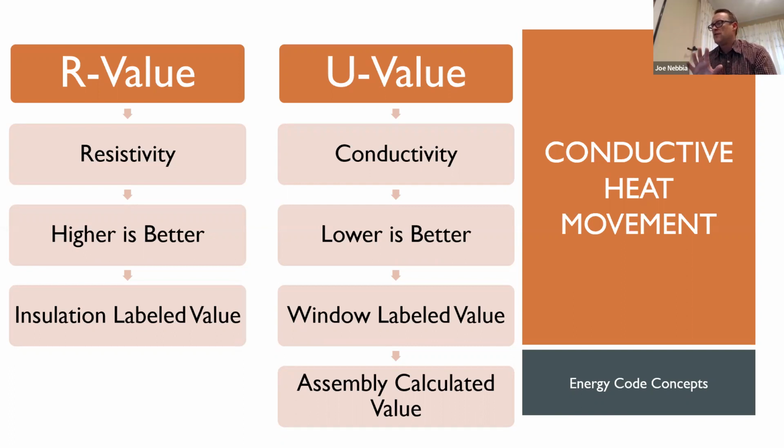If you find a material that is being advertised as having an effective R-value higher than its labeled R-value, that's not going to work for code compliance. So, sometimes I've seen manufacturers that have an insulating product that also air seals, and they say, well, this has a labeled R-value of 18, but it's an effective R-value of 24 because of the air sealing.